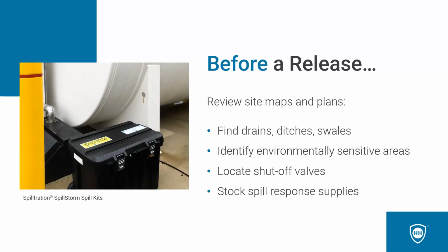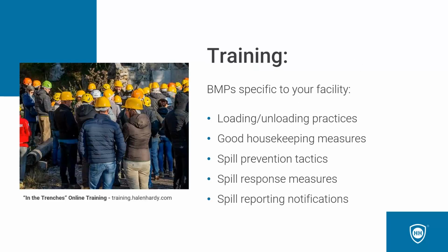Is there a ditch near the area? Is there a drain near the area? Where are the vulnerable locations? Look at those on the map, outline them, highlight them, know where they are, because if we don't know where they are, we don't know where to be prepared. Mark them on the maps if they're not already there. And in a lot of municipalities and a lot of states, those things are actually required on your site maps anyway. So that homework may already be done for you.